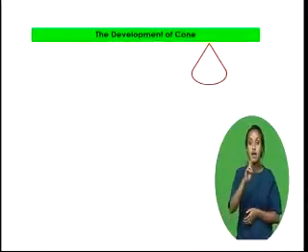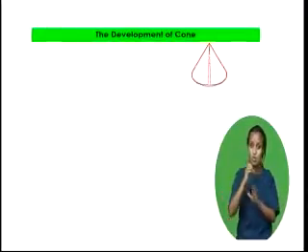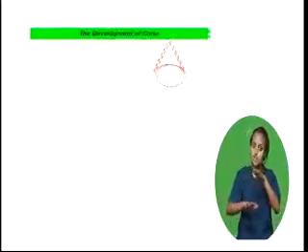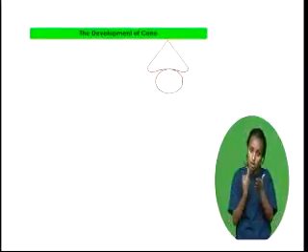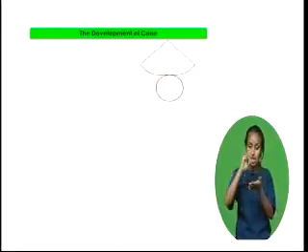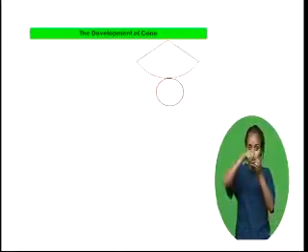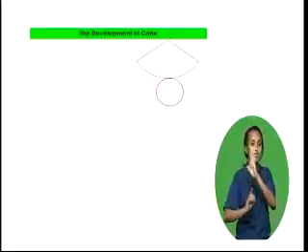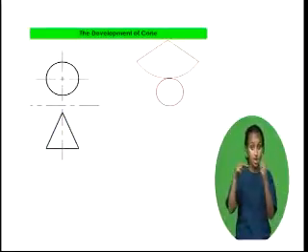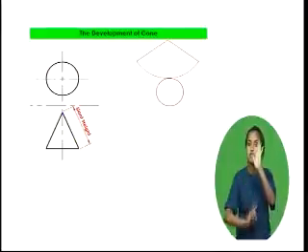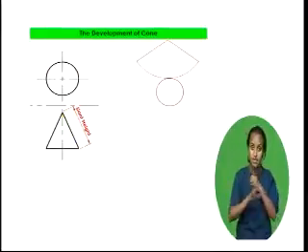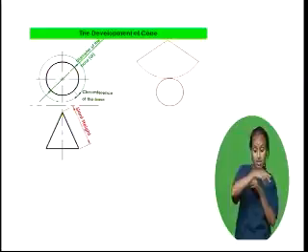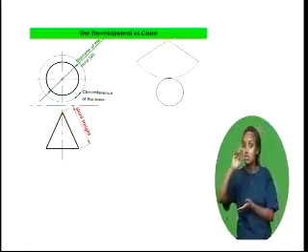Radial line development is employed for pyramids and single curved surfaces like cones, in which the apex is taken as center and the slant edge or generator as radius of its development. The two dimensions necessary to make the development of a cone surface are the slant height of the cone and the circumference of its base.